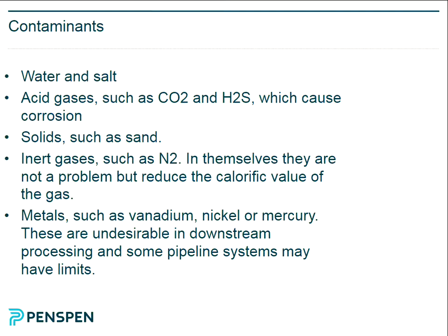Among the contaminants is CO2, carbon dioxide. But we also know that some fields are produced using CO2 for enhanced oil recovery. Yes, that's right. Is it a trade-off? Yeah, swings and roundabouts. If you pump loads of CO2 in, then you might increase the CO2 coming out. Now, CO2 and water produces carbonic acid, which is corrosive to a pipeline. So you're right, CO2 is used as a production enhancing technique, but then it may enhance your corrosion issues.